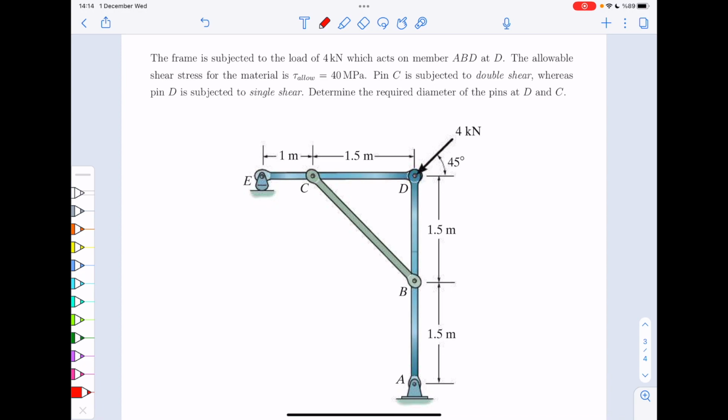Okay, all you have to do is to basically draw your free body diagrams for each piece of these. For the horizontal piece, here you have E, and then you have the force EY. Then at C, you have your T. Remember, BC is a two-force member, so you get T on both ends. At D, you get dx, dy, that we don't know what they are. But whatever they are, their reactions would be in this other member.